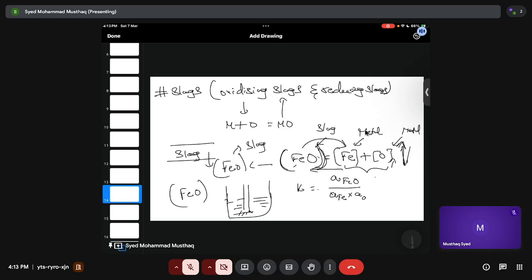This is very much important in steel making technology. We need to keep an eye on time, because this happens for a respective amount of time. Initially you have oxidizing slag, and then you have emulsion. Once the whole carbon gets depleted, you will not find emulsion, because there is no formation of gases to form emulsion with your slag. So this is one great property of slag in steel making. The next property is sulfide capacity.